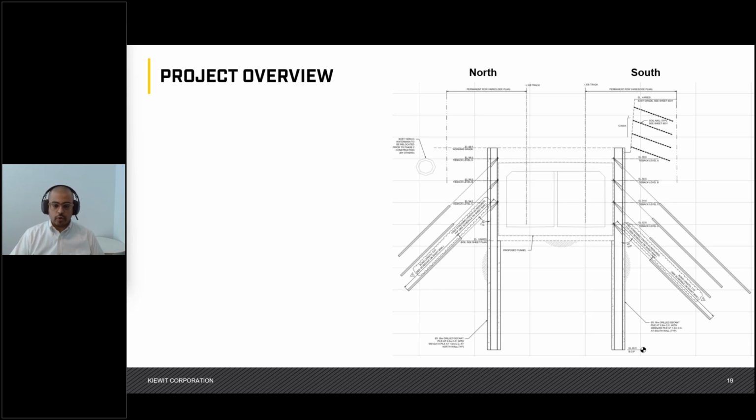Excavation for this tunnel was a maximum of 13 meters deep, and many different types of supportive excavations were used along this alignment, including soldier pile and timber lagging, secant walls, lock block walls over vertical rock cuts, all sorts of supports, including struts, tiebacks, you name it. Essentially, any type of supportive excavation was probably used on this project.